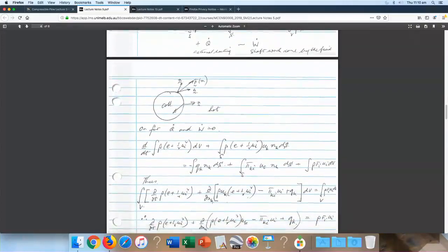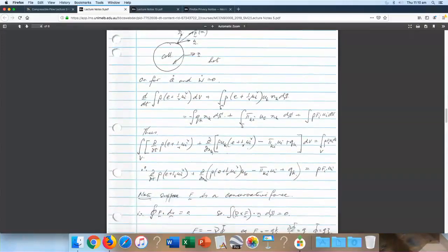so this is where I worked it out for you, and I really used the Reynolds transport theorem to get from the moving volume to a fixed volume. And there it is, that's the rate of change of energy in the volume, plus the flux of energy, so that U_k is simply U dot N. You know, N has components N1, N2, N3.